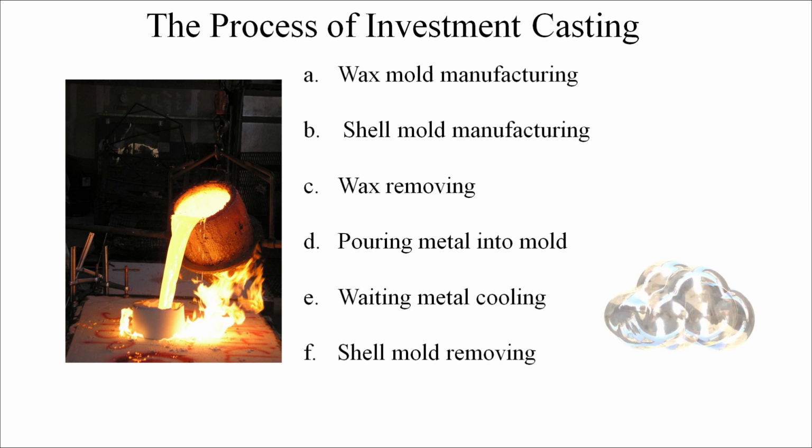a hollow interior. The high-temperature metal is poured into the interior space of the shell and fully fills all crevices and voids. Wait for the metal to cool in cooling water until fully solidified and hard. The shell can then be broken to finally obtain the cast workpiece.